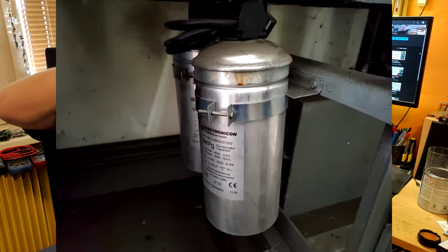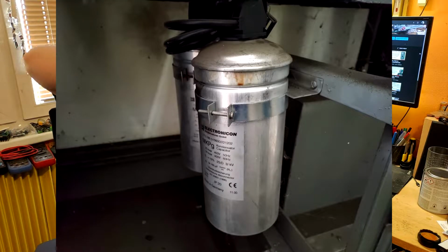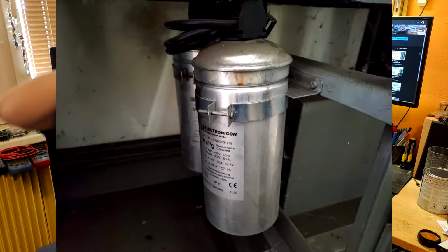To compare it, overvoltage is like nothing compared to THD overloading. If for example you have 400 volt rated capacitors and you are feeding them with 410, 420, it's like nothing compared to huge THD, like 5% or so. So overloaded caps, if they are good quality, just get hot, they inflate, and as they inflate, they emergency disconnect themselves from the network.